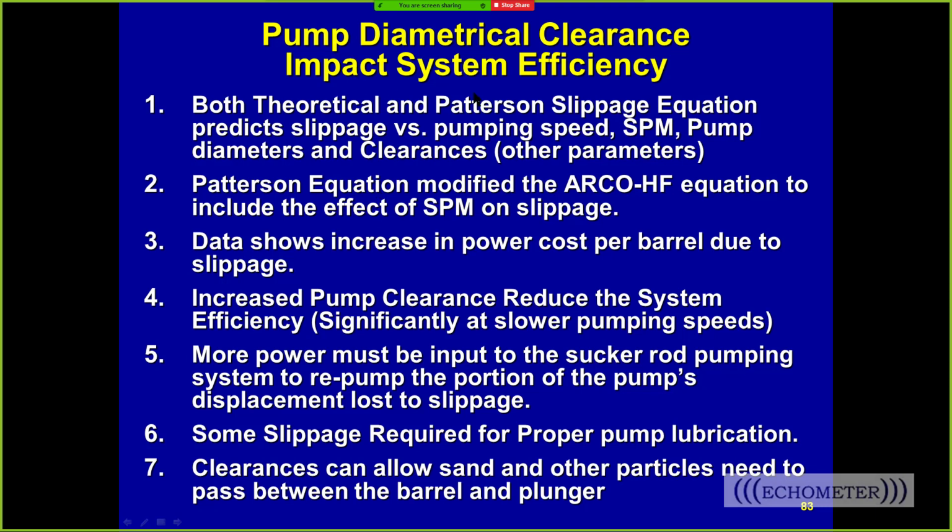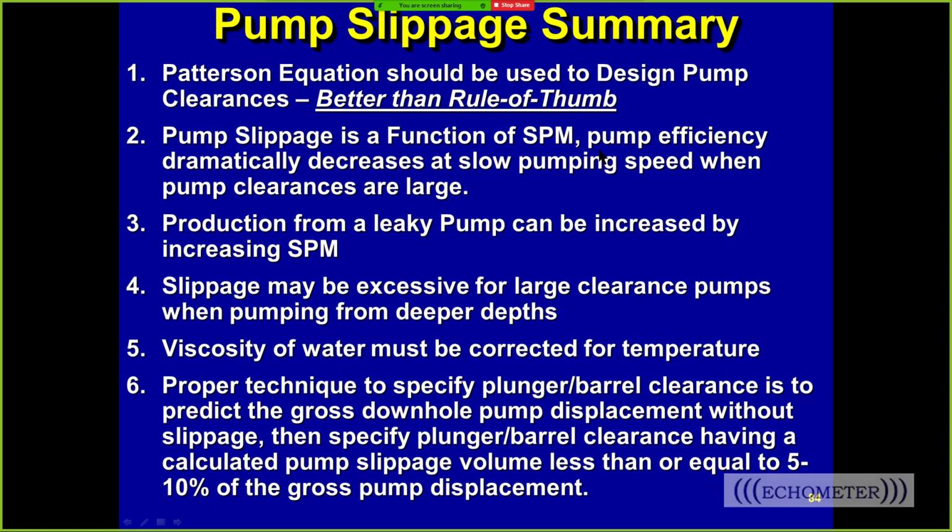The Patterson slippage equation is a lot better than using a rule of thumb. Slippage impacts efficiency of your pumping system. It reduces your pump displacement because of slippage. You have to put in more power. You need some slippage for lubrication, and you may want to consider more open clearances to pass solids. So all those are important.